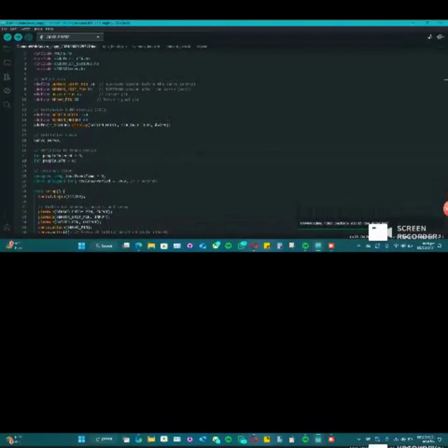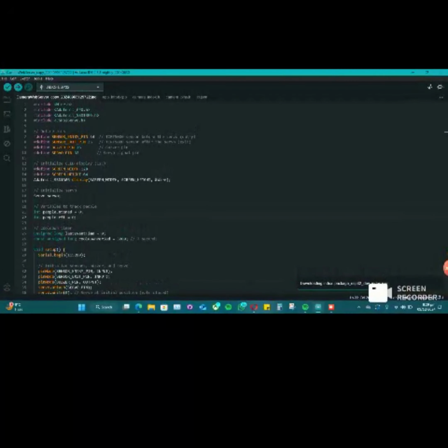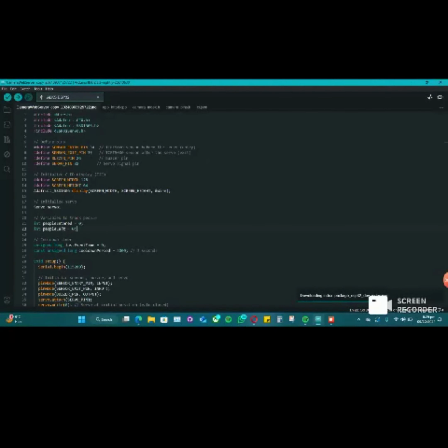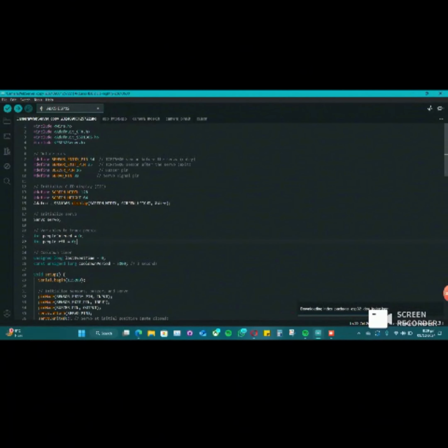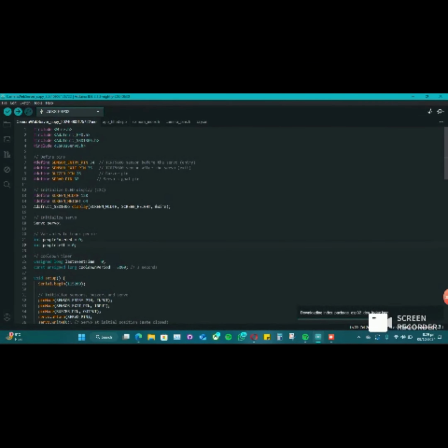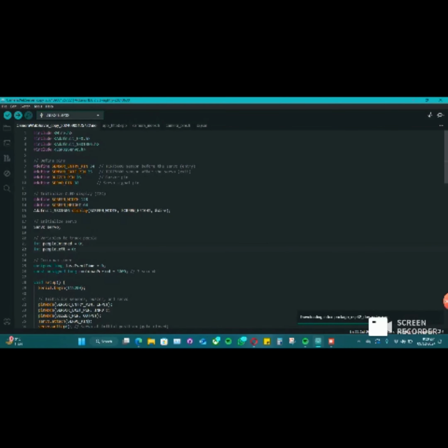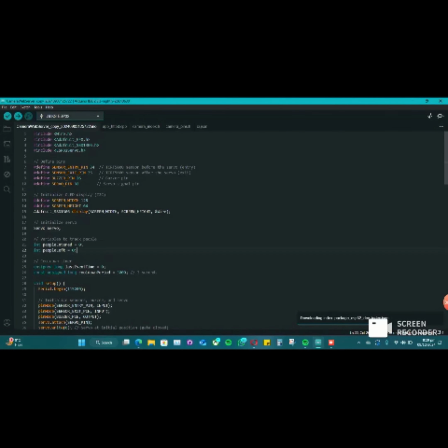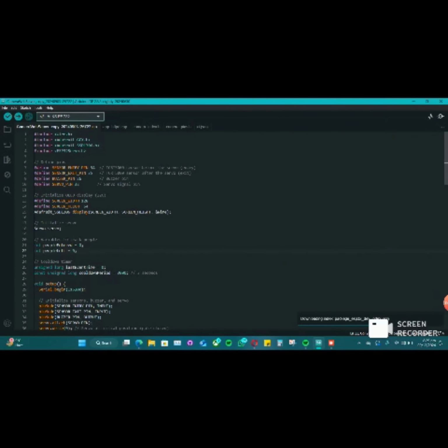Now I'll explain how this program basically works in order for our project to successfully implement its function. We'll start off by including several libraries to handle hardware components. As you can see over here, we're including four libraries, one is Wire.h, followed by some other libraries, including ESP32Servo. The first library is used for I2C communication with the OLED display that we have on our breadboard, and the other two libraries are used for controlling the OLED screen. And the last library is obviously to control the servo motor that is responsible for opening and closing